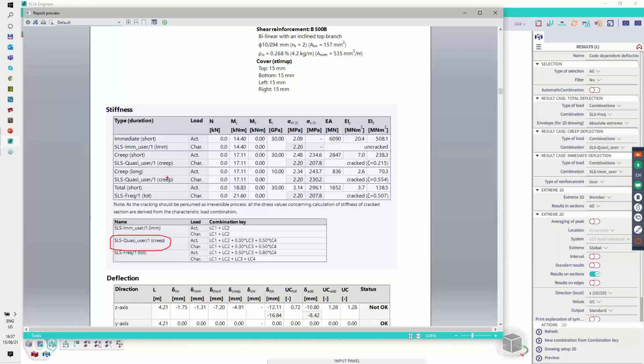Okay. And here, for instance, you can see that before, for automatic generation of combinations, we have all sections for all load sets actually with the correct section in the middle of the beam. But here you can see I changed the load level. So now my tensile strength of concrete is below the limit. So actually I have an incorrect section in this case. Okay.